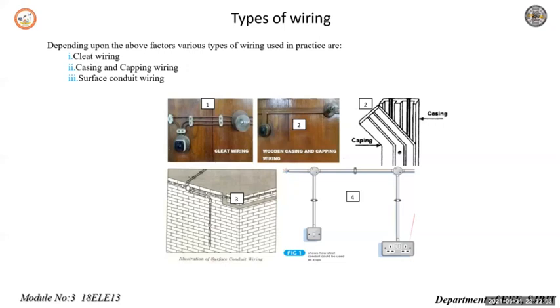This type of wiring is cheap and can be used in residential wiring. So the advantages are it has a good appearance, is simple to erect, is cheaper in cost, and provides protection against fire, high temperature, etc. What are the disadvantages of it? Wires are always exposed to the atmosphere and hence subjected to dust, dirt, fumes, and other dangerous atmospheric conditions. Bending and breaking of the batten, and hence of the wires, may occur after some time. These are a few disadvantages to list.